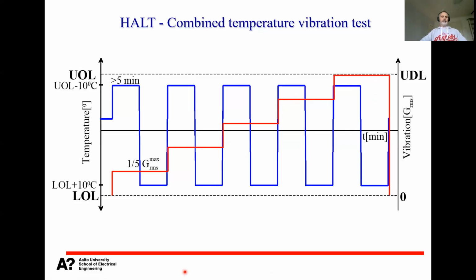So you can understand that this now is extreme testing. Basically you have your product, you are simultaneously shaking it in all directions, and you also go temperature upwards and upwards and upwards, or cyclically upwards and downwards, and so on. So it means that if your product can withstand this, it will become quite robust. It's easy with this kind of way to find out the weakest links. What would fail? And then the question is, are these failures relevant or not?